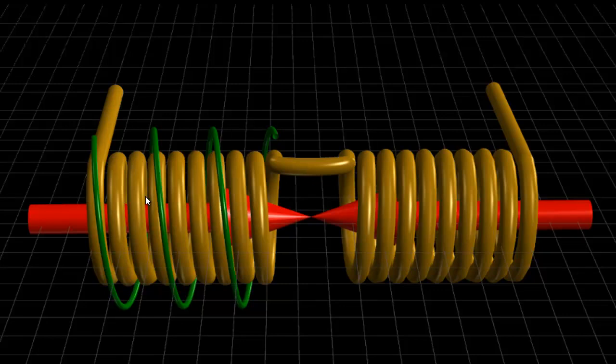And again, the factors of the electromagnetic induction between the secondary coil here and the tertiary coil over here, electromagnetic induction between these two coils must be thought about. Okay, we need a wire gauge, we need a cross-sectional area, we need a number of turns so that we can actually try to get the voltage on the terminals as high as possible within reason. We don't want to go silly again. We need to protect ourselves, 10, 15 volts or something like that. That's all you really need to start off with, just enough to light a globe or something. But this is what we need to start thinking about.